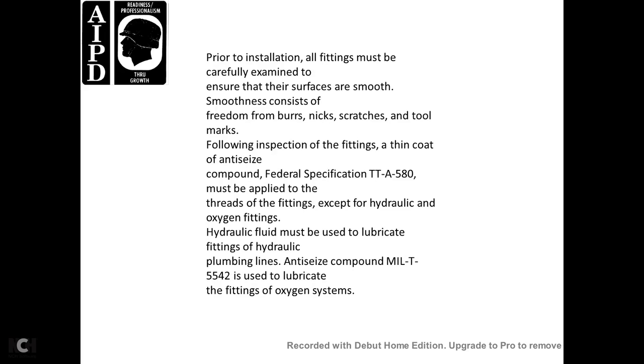Following inspection of the fitting, a thin coat of anti-seize compound, Federal Specification TT-A-580, must be applied to the first three threads of hydraulic fittings, excluding oxygen fittings. This compound is used to lubricate the fittings of the hydraulic plumbing lines. Anti-seize compound MIL-T-5542 is used to lubricate the fittings of the oxygen system.